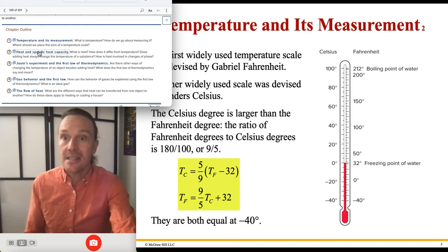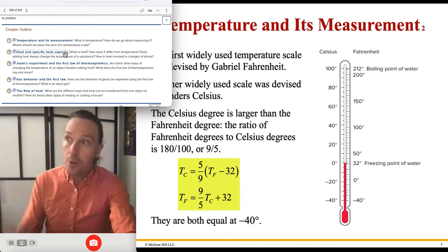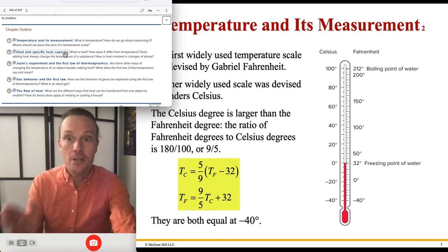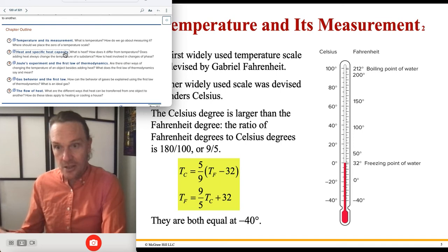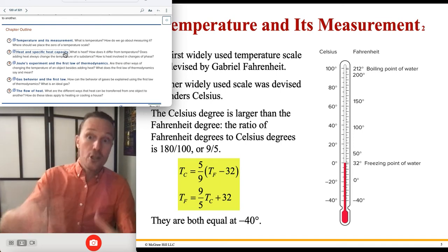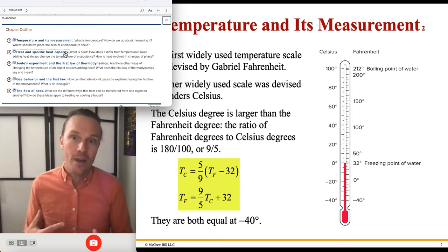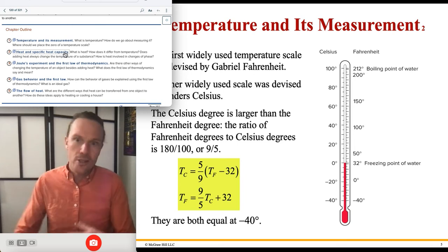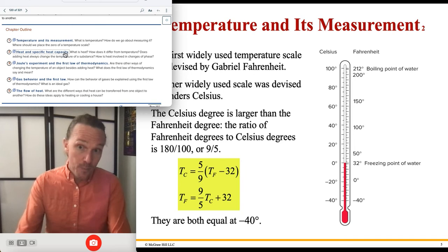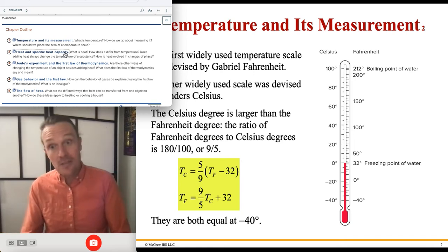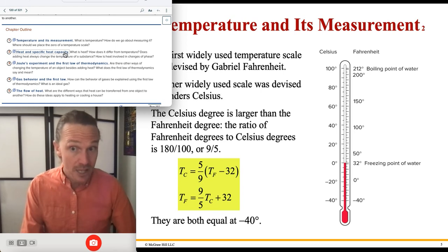And the first one of those we're going to see is this thing called specific heat capacity. It turns out what it actually is, it's energy per degree change per kilogram. So how much energy it takes to change a degree for a certain mass of something. And so I say it's a material specific or substance specific quantity in the way that you ask yourself, is it water, is it oil, is it hydrogen gas, what is the thing that you're putting heat into? Well, then you know its specific heat capacity, you know how it behaves and how it behaves differently, because it turns out some things require a lot of energy to heat up, other substances don't require so much energy, okay?